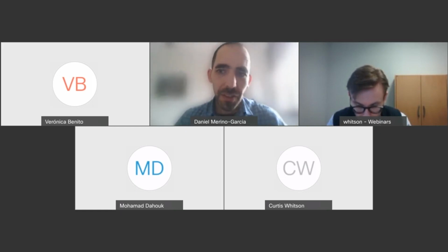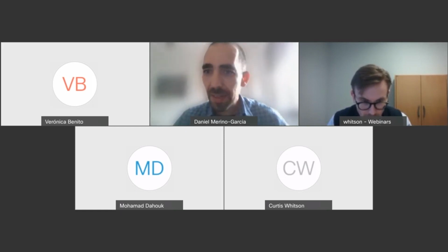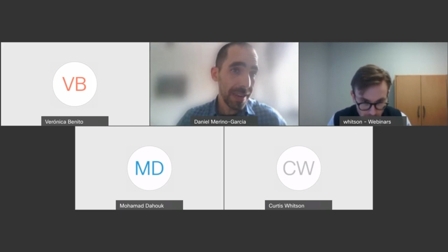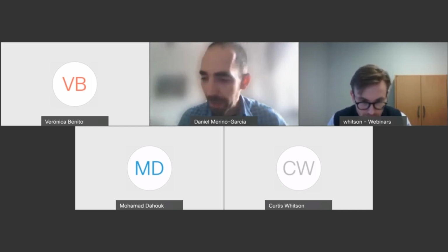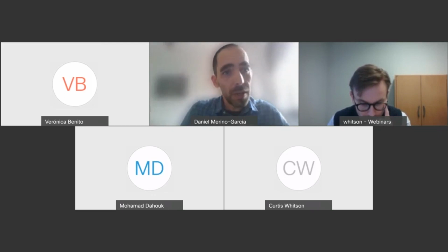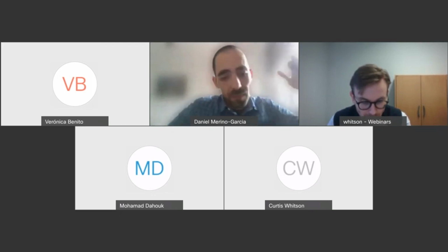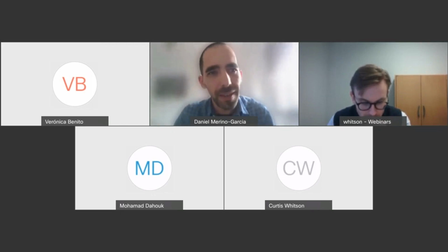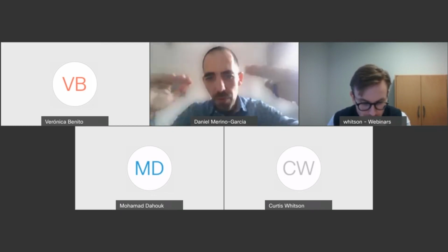So I would say yes, a unified equation of state should be the goal in every single reservoir. They're also asking about subsurface versus surface. I believe that separator tests plus experiments closer to the reservoir, you can tune them together, no problem. I understand the issue could also be the number of components in that equation. Typically we generate one full-range equation of state, and later the reservoir team may want to work with a reduced number of components. Maybe that implies extra tweaking, but we still have that reference unified view for everybody.